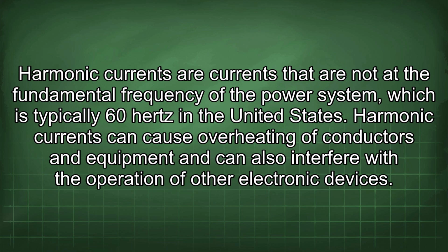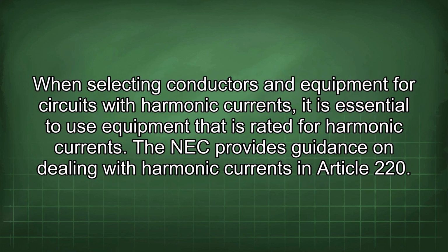in the United States. Harmonic currents can cause overheating of conductors and equipment and can also interfere with the operation of other electronic devices. When selecting conductors and equipment for circuits with harmonic currents, it is essential to use equipment that is rated for harmonic currents. The NEC provides guidance on dealing with harmonic currents in Article 220.